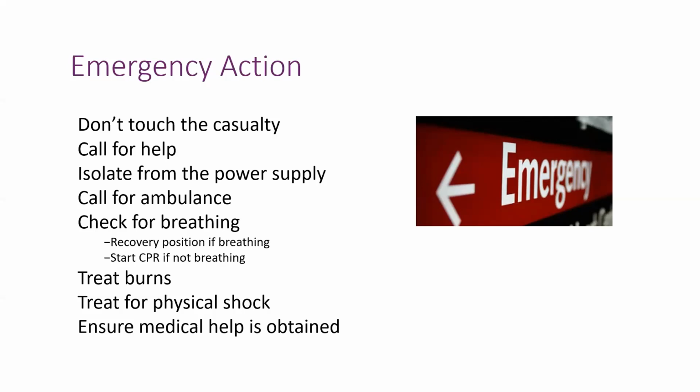Don't touch the casualty, because it might be possible that there is still current within the body. So we need to avoid touching the casualty. Sometimes we get too sympathetic with our friends or colleagues. He is in contact with electricity, and we want to throw him away using our own bare hands, which means that we are also getting electricity transferred. So whenever a colleague or any other person comes in contact, we need to avoid touching the casualty.